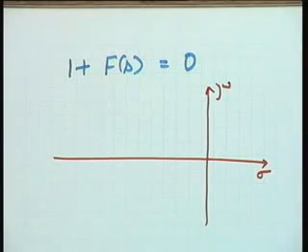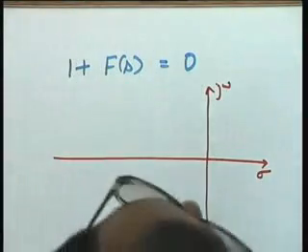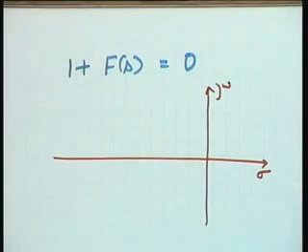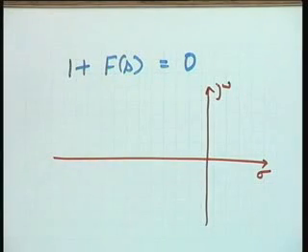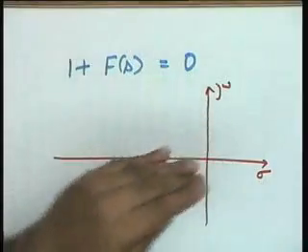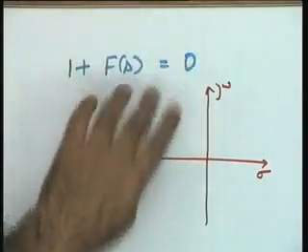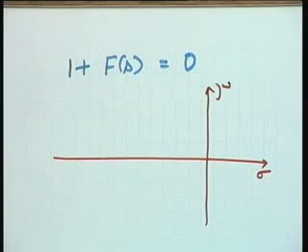This is the definition of the root locus plot. You have to scan through the entire S plane and join all those points appropriately, so that for a particular parameter which is varying from, let us say, 0 to infinity, if you find the roots of this particular equation, then that particular plot becomes the root locus plot.